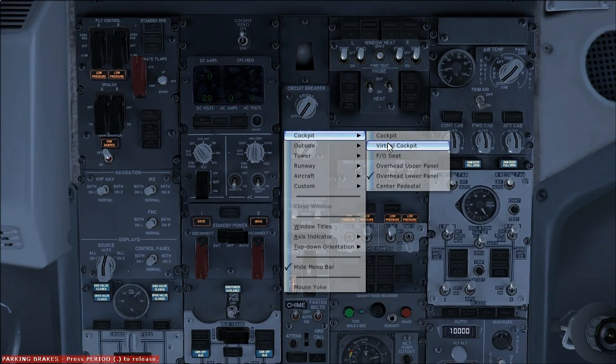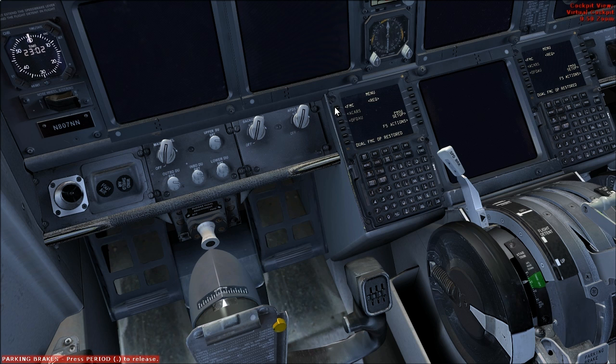And then we need to go back down to our CDU into our FMC, and position initialization. Just grab the GPS position and set that. And then we can set our reference airport, which is Los Angeles International Airport, KLAX.